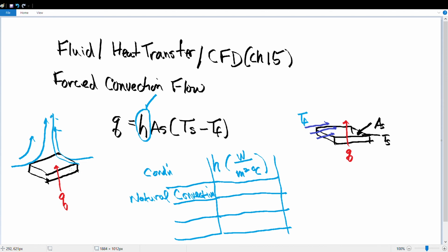So cooling by that is not as good as if we force air over it, right? But it's something. It's kind of Mother Nature's way of keeping things from overheating. As the air heats up, it rises because it drops in density, and that's called natural convection. You have to have gravity for that, so this can't occur in space, for example. If you're on the International Space Station, this won't occur. The air just kind of forms a blob up here and doesn't move. It could heat up, but there's no gravity to aid it in moving out of the way.